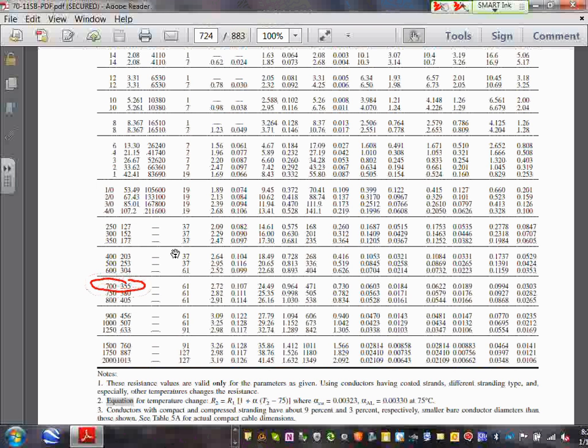The 687, you said down or you said up? You size up. That would be 750 because that's 355. Well, wait a minute. We came up with our size was 687.5. You go up to 700. Yeah, you go to the next standard, and the next standard. Oh yeah, I should have put the KCM here. The next standard is right here: 700 KCM. Any comments, guys? Any questions?